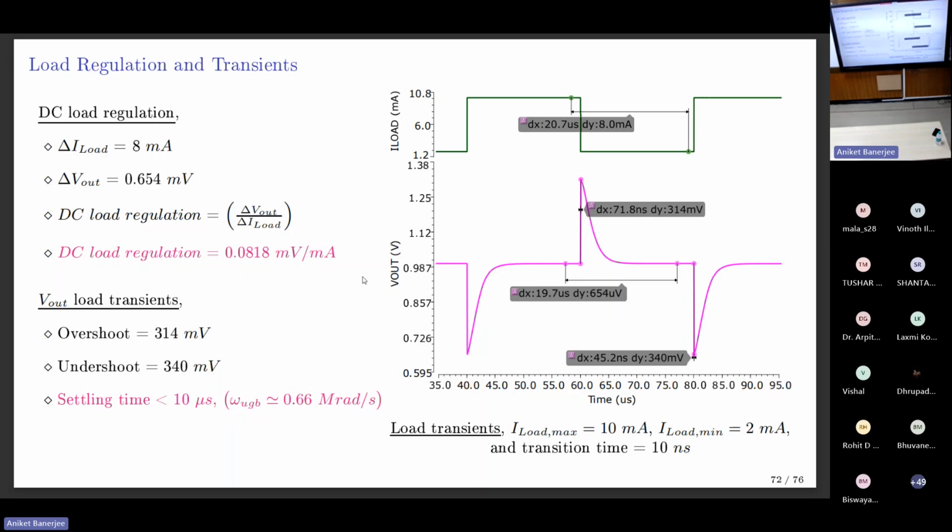Where I'm going is, today, if you look at industrial class designs, it's typically a hybrid, which means you have bipolar and MOS, again for flicker noise and other reasons. So at some stage, you may start degenerating, or you actually build a hybrid bipolar-MOS for very high-end industrial designs. I would imagine gm/ID may still be applicable on bipolar. There was nothing intrinsic that said you can't do it on bipolar. But at some stage we start degenerating, especially for intrinsic component noise, and you have to start tweaking this process. That's what I mean.